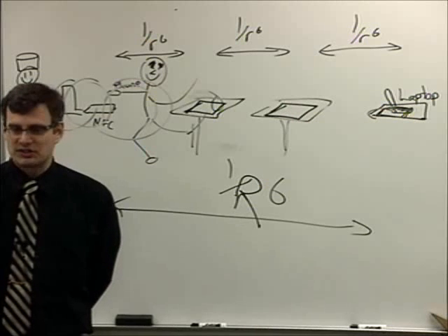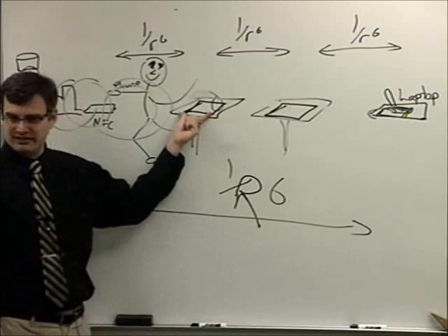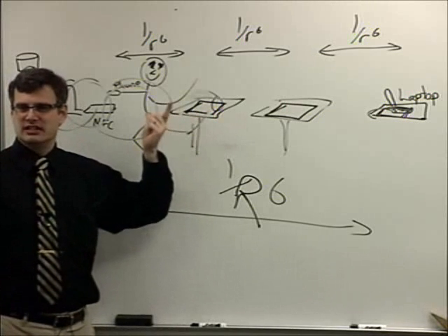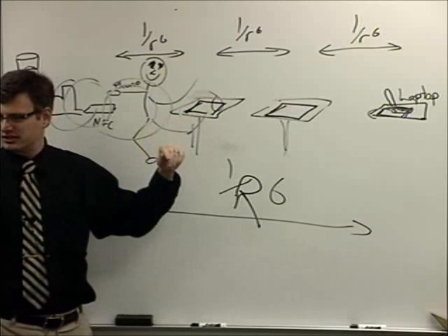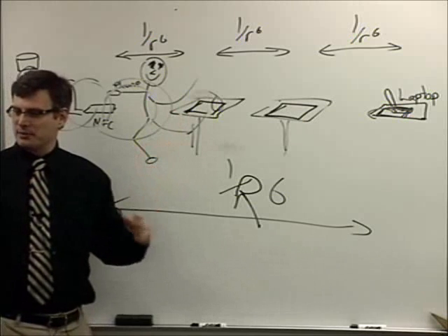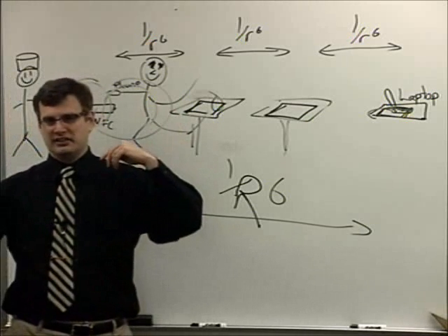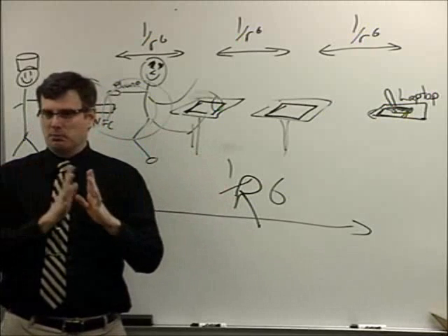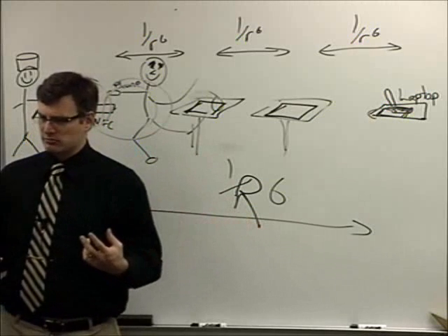Well, most of the devices that your phone connects to, this is actually a very narrowband device. So if you're doing this kind of near field coupling, it is only at 13.56 megahertz plus or minus a few kilohertz. Right. But if you're talking about, I've got a Bluetooth, I've got a wireless LAN, I got a cell phone frequency. Those are all a broad band of much higher frequencies that you select, and that's a different mode of communication altogether.